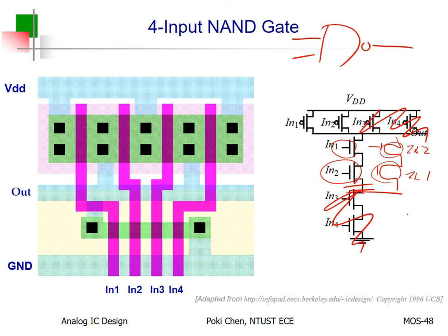Got it? You need to be so picky. Then you will become very outstanding in the future design. In this way, one half here, the other half there. So you have some kind of cross-coupled connection for your input. Then you can make everything perfect to enjoy the same delay.